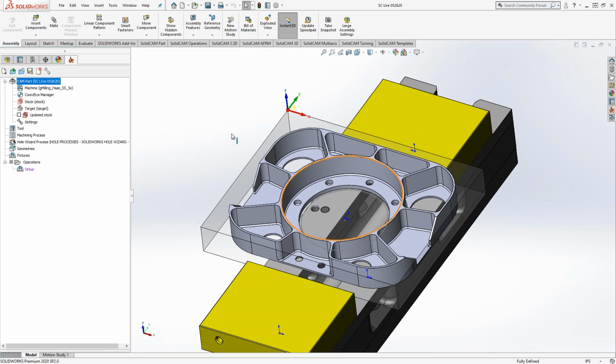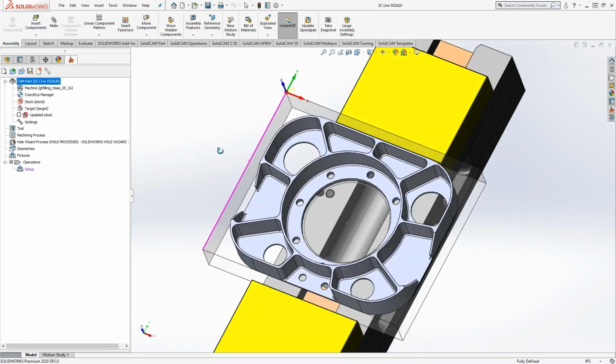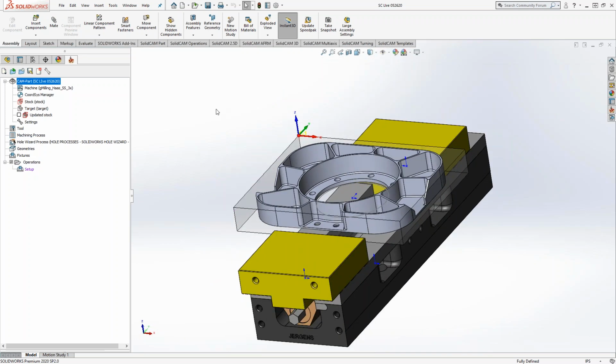And I'm actually going to take you one step backwards, Mark, and give you a little explanation. Maybe we won't even get to putting on toolpath today, but on a particular part like this, when I would be out on the shop floor machining this part, what I would do, for Mark's stock, he's got it up to size right now. What I would actually do is add an additional 10 thou of stock on there, just for the model. Now, when I go to cut it on the saw, I would cut it right up to my exact size.